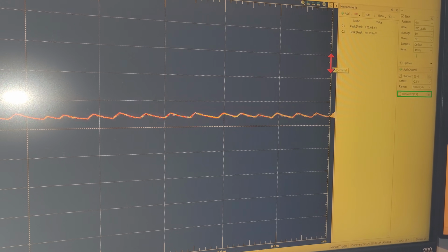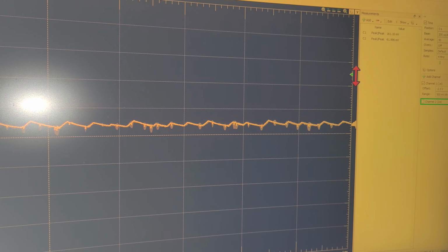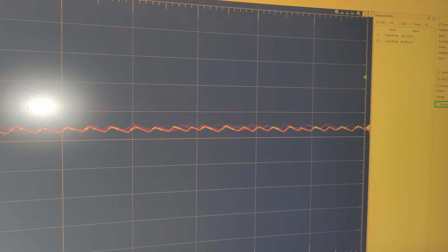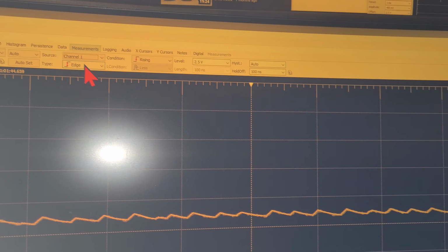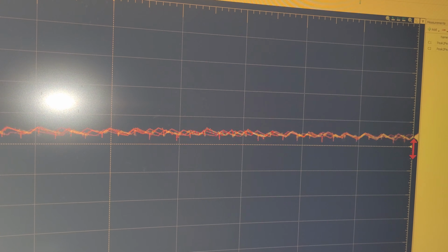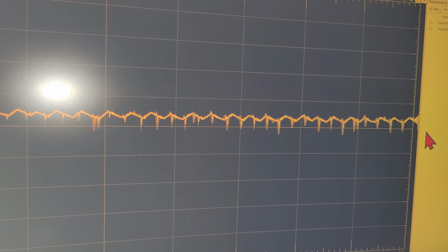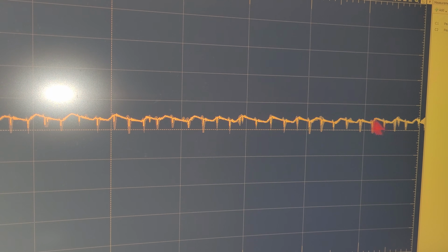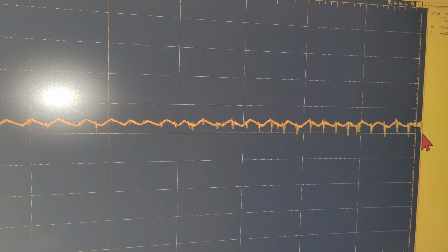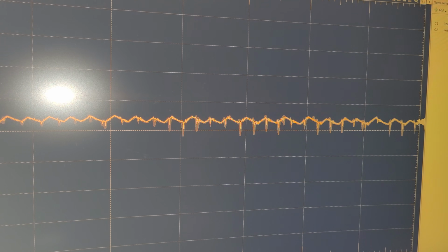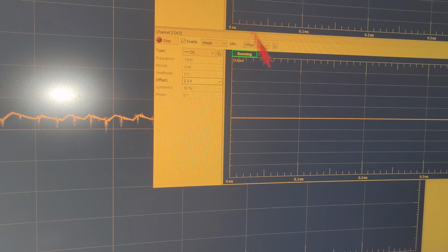We're going to want our trigger level, which is the triangle on the right. We want it first to be on channel 1 because that's what we're dealing with, so we're going to change that at the top right there. And then we want it to be inside of our waveform right there. So it's going to be channel 1 inside of here. We can see the averaging is on, and now we can turn our supplies on as well. So we're going to click run all.